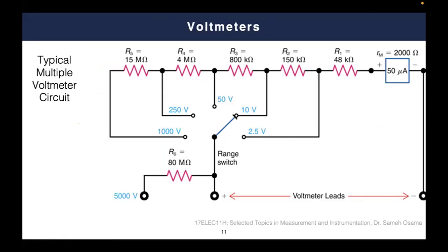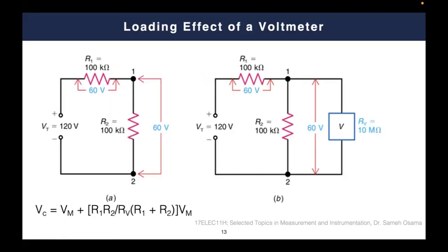You can do so. So what you can do simply, my dear students, is to go with a very high resistance. Let's say in the mega ohm range. So principally, there is still an error, because now 100K ohm parallel with 10 mega ohm is not 100K. It's slightly less than 100K, but it's slightly less.